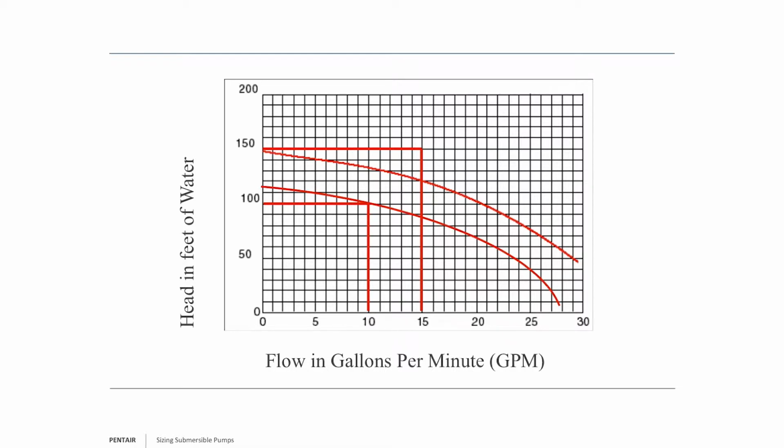If you said, but Dan, you talked about trimming the impeller, or changing out the impellers, the answer is yes, you can do that. But understand, once you do that, when you trim an impeller, when you change the impeller stack, for the A and the B and the C, understand you change the whole curve. That means, let's say this customer who wanted 10 gallons per minute, 100 feet of head today, decides to add a second zone that needs another 10 gallons per minute, 100 feet of head, and they want to run both zones simultaneously. Once you trim an impeller, you forever cut that impeller.